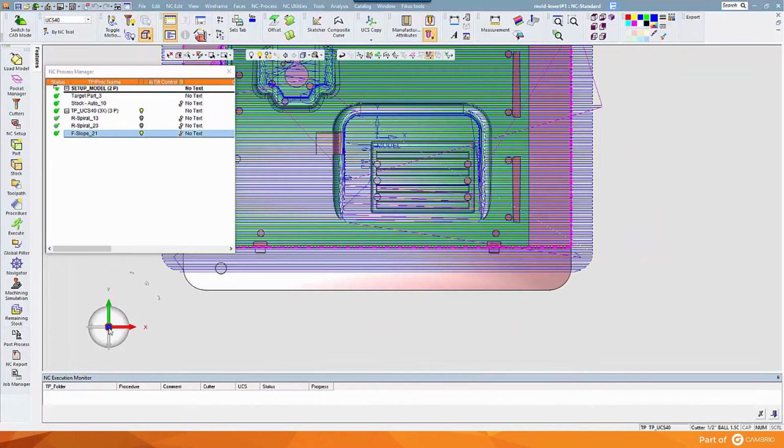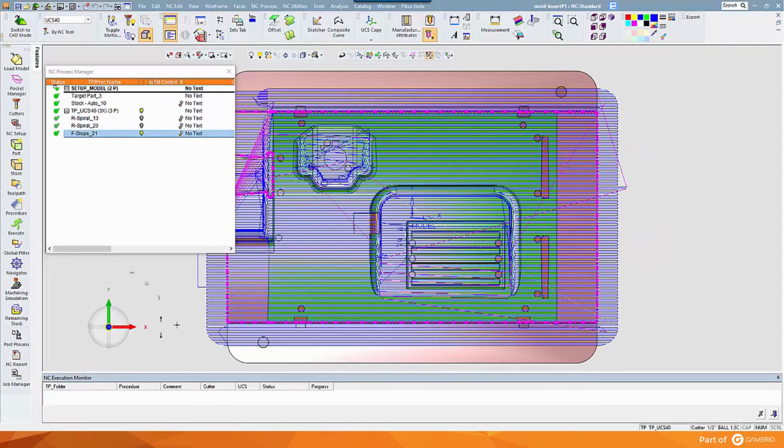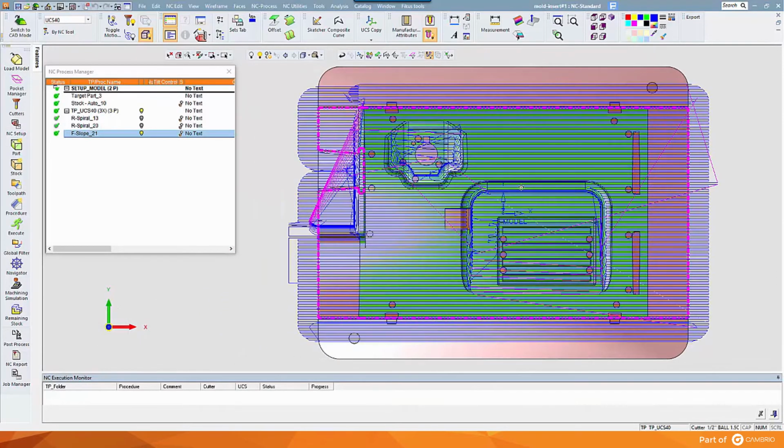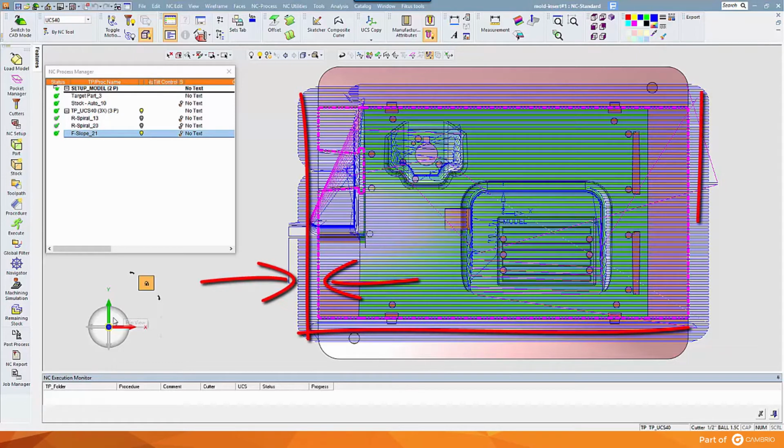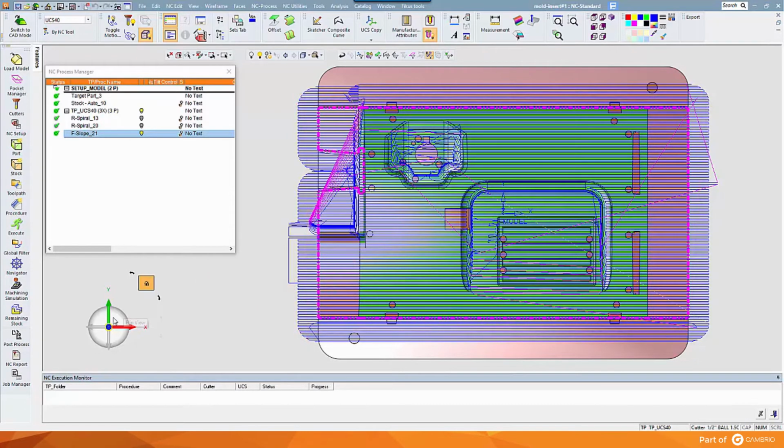This creates automatic extensions on the toolpath at the outer edge of the selected faces. It's only offered if the automatic boundaries are used, and it's only available for parallel motions on horizontal regions. Machining expansion may be defined as an air extension or a surface extension, or both. Surface extensions require overlap faces be defined as part surfaces were.